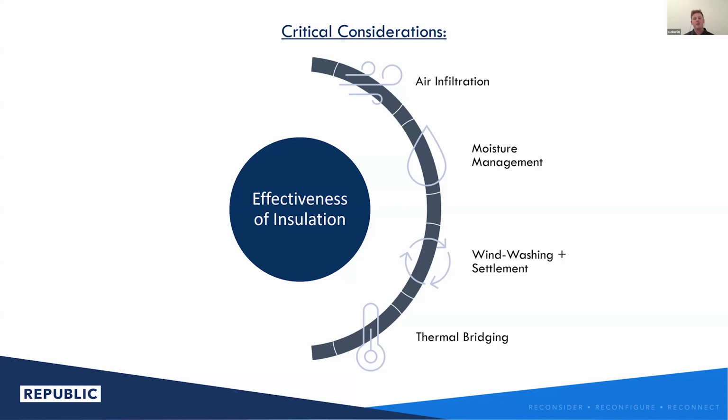Another thing here, which I think is maybe lesser modeled or lesser factored, is wind washing and settlement. Especially on loose fill or dense pack style insulation, making sure that the material is understood in terms of how it will settle, and how it could potentially be moved by the winds that move through an attic space as the building breathes and lives, as well as really understanding thermal bridging.